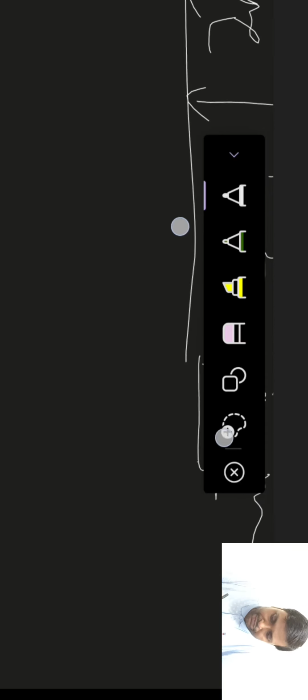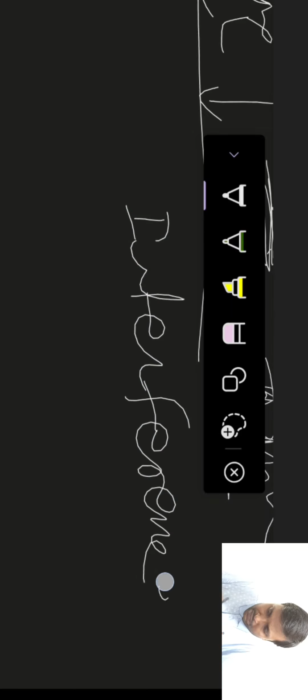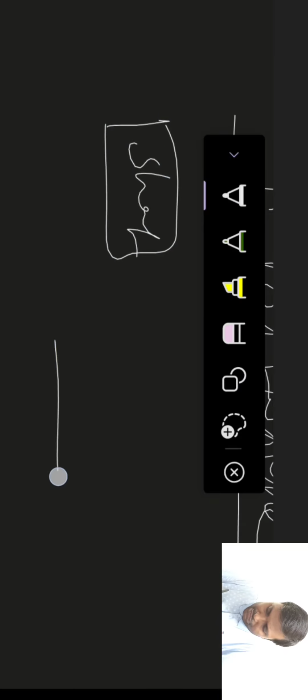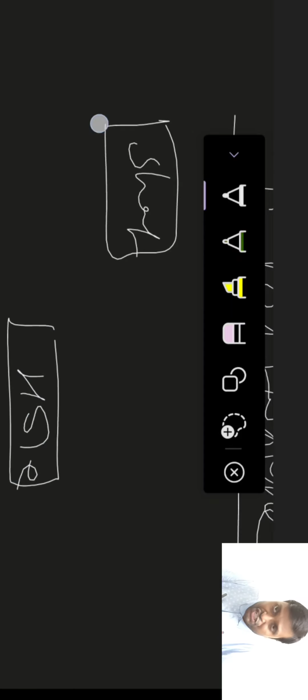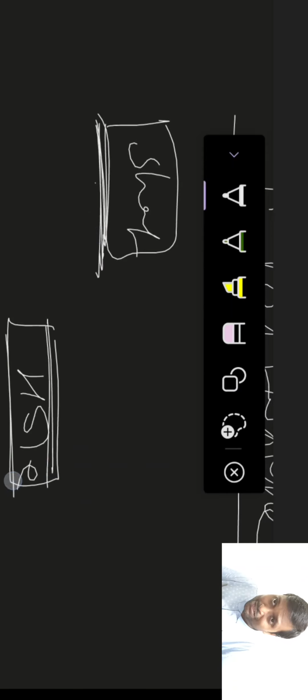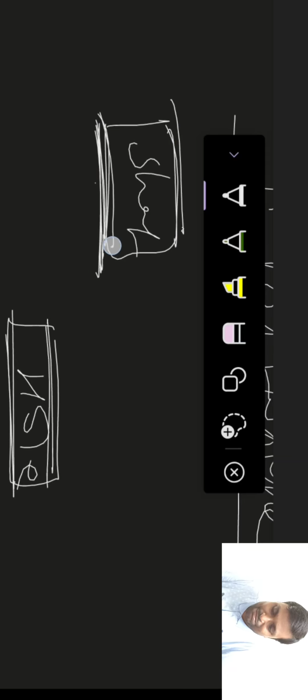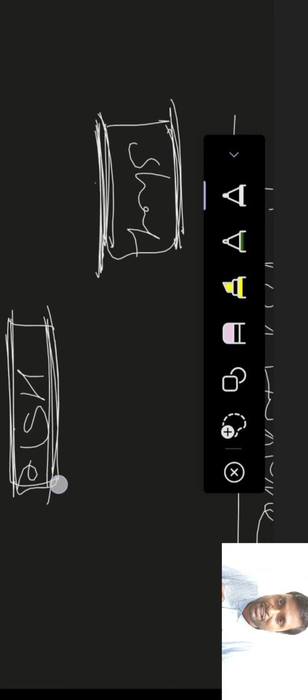Now come to the interference fit. Let this be the shaft and this the hole. The smallest shaft is greater than the largest hole, so this smallest shaft will be greater than the smallest hole also. The largest shaft will be larger than the smaller shafts, and therefore greater than any of the holes.